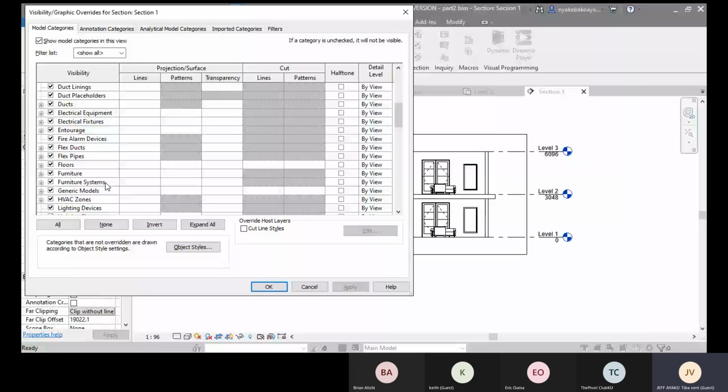Under the analyze here, you can set your location. So you can set the location to which you are going to do this project. So the location where you are constructing the building. So it takes some time. By default, it's set to Boston, but you can look for your location.